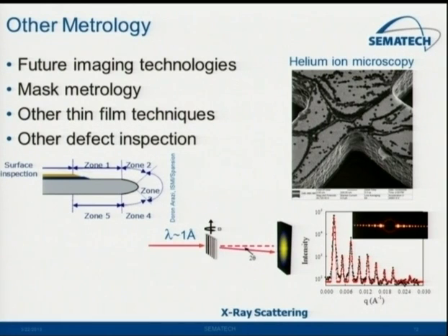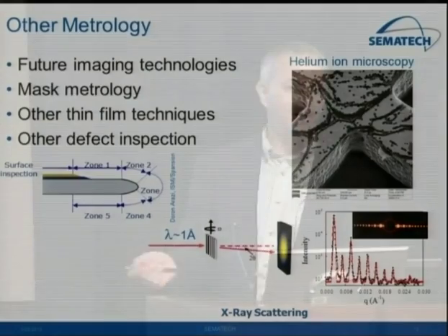Or other things, like maybe today people are starting to look about defects around the edge of the wafer. Defects that may be right near the top of the wafer, on the very edge, or even on the backside. So those tools are also starting to come into use. Usually based on the same types of techniques I showed, either like a dark field scattering or imaging technique, but deliberately trying to do it across a surface that may not be specularly flat. So a lot of opportunities with regards to metrology.